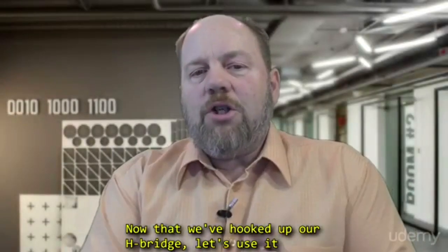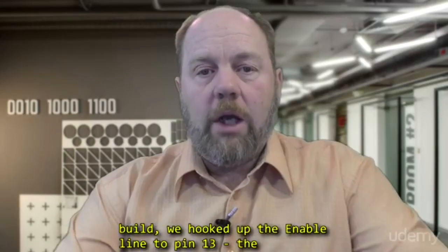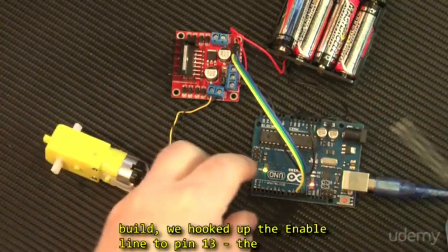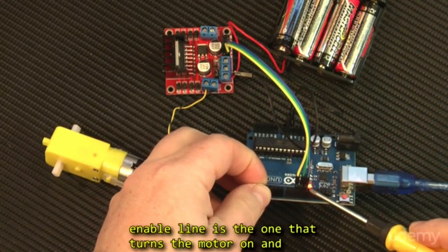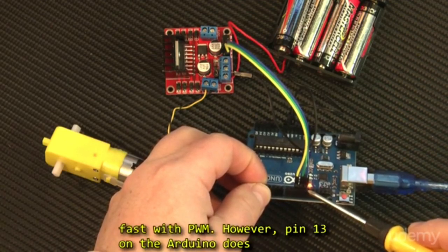Now that we've hooked up our H-bridge, let's use it with pulse width modulation. In the last lesson build, we hooked up the enable line to pin 13. That enable line is the one that turns the motor on and off. So we're going to turn it on and off really fast with PWM.